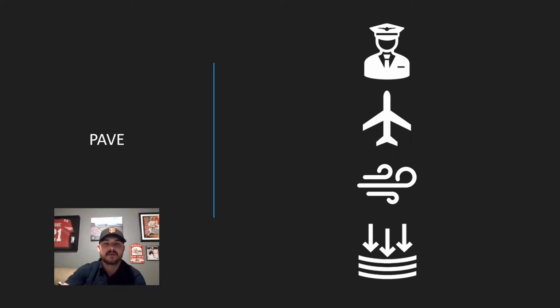A is for aircraft, including performance, equipment, and airworthiness. We'll need to go through a pre-flight checklist with the aircraft to ensure it meets all the maintenance requirements, check to ensure it has all the required documents, do our various calculations, and more. I'll also consider if I have the necessary familiarity with the systems and instruments. If I've only flown a round gauge plane for months, I probably shouldn't hop into a G1000 Cessna expecting I'm still proficient in flying the thing.